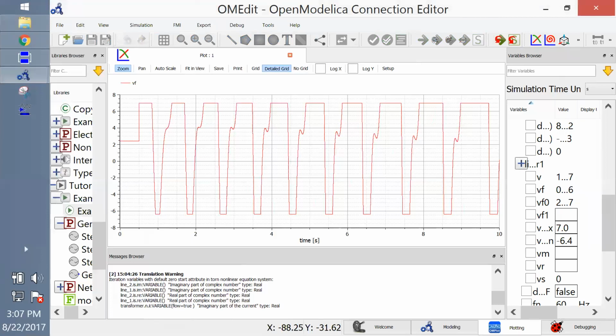Now you can actually study what they show you in the dynamics courses, the stability of the numerical simulators and all that stuff. You can make the time constant of the AVR as small as your model time step, and that thing will not run. It will start oscillating, but that's not a system oscillation. That's a numerical problem. Okay? So it actually is quite fun, because then you start thinking about how you should simulate things, instead of just dragging and dropping the stuff.